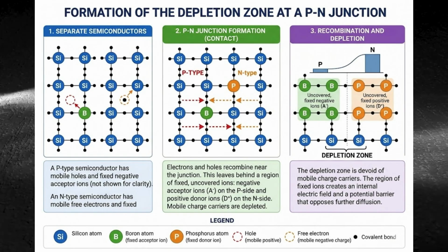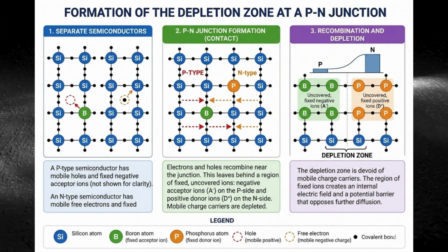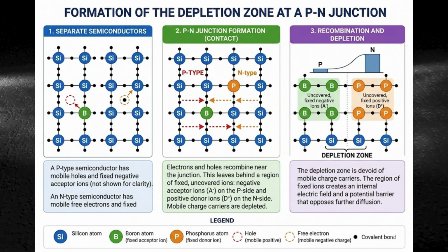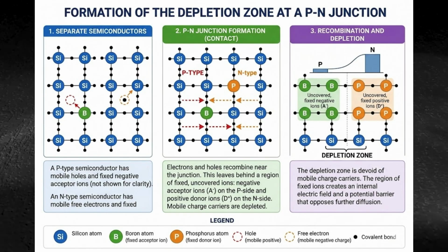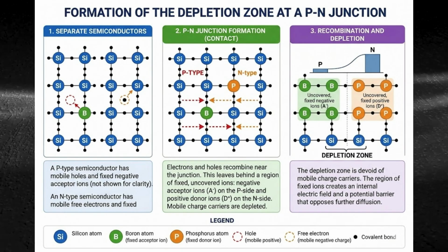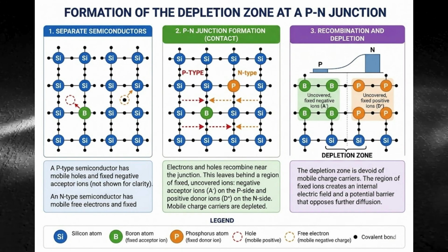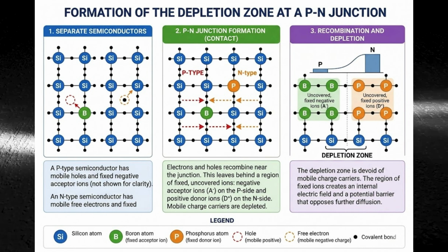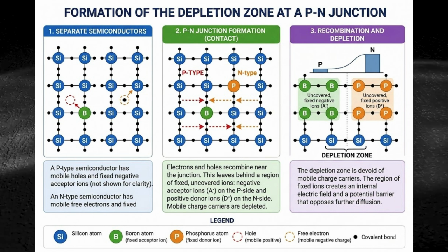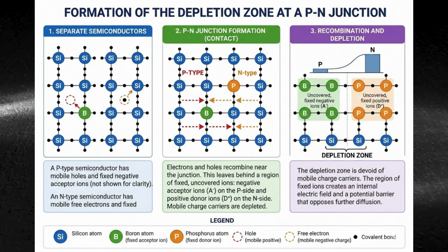When the p-type and the n-type regions come in contact, charge carriers begin diffusing across the boundaries. Electrons move toward the p-type and holes move toward the n-type. This diffusion creates a region depleted of free carriers called a depletion region, and inside of this region, an internal electric field naturally appears. This electric field is the mechanism that allows the solar cell to function.